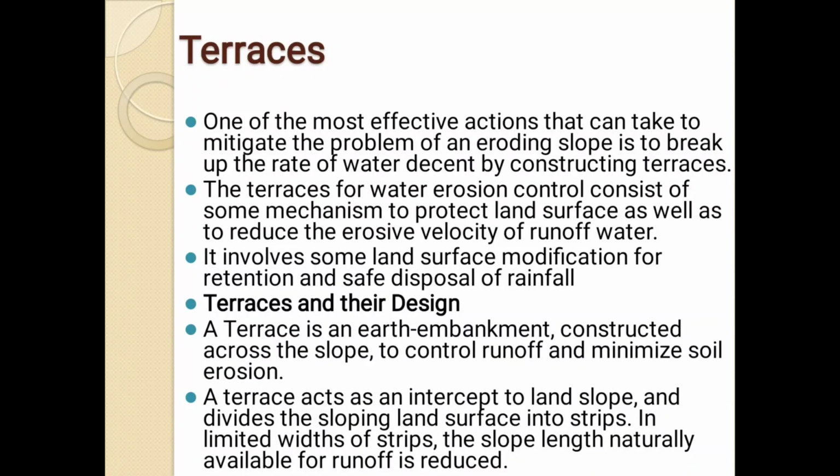Next one, the terrace and its design. A terrace is an earthen embankment constructed across the slope to control runoff and minimize soil erosion. A terrace acts as an interceptor to the land slope and divides the sloping land surface into strips of limited width. The slope length naturally available for runoff is reduced.